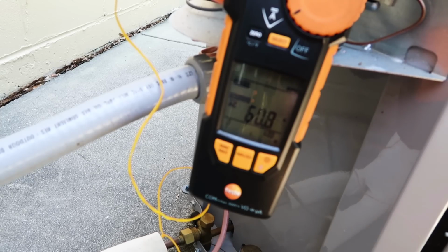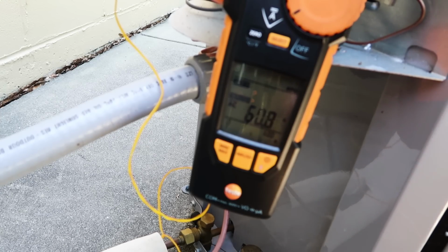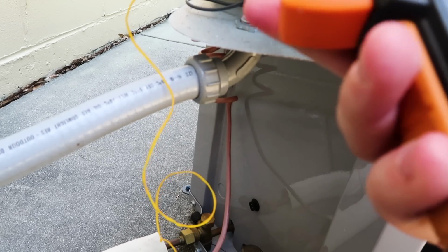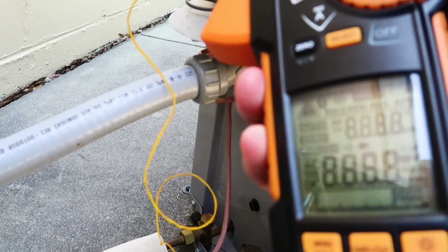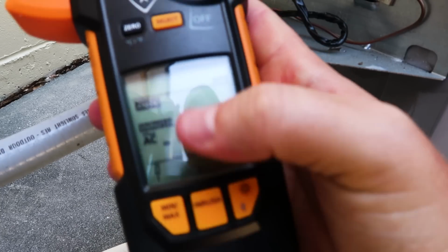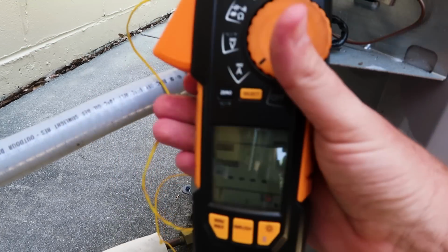What you see on common is start plus run, right? So you get that. So let's now measure the inrush amps on common to help additionally prove that all of the inrush is on run and not on the start winding. Inrush, there we go. All right, now.